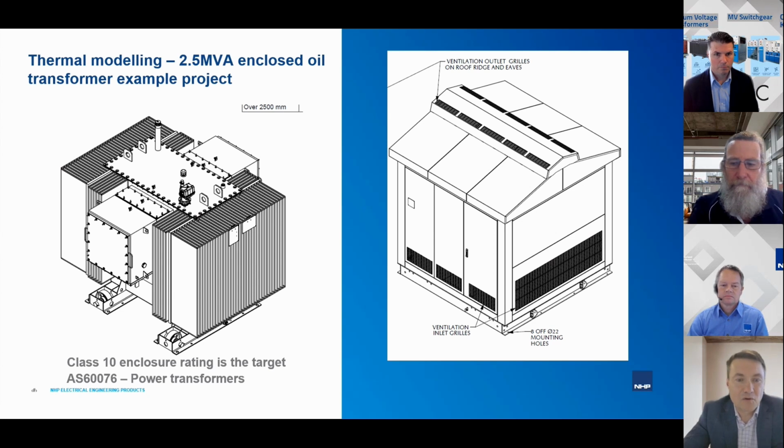So therefore, the transformer was not designed to accommodate additional temperature rise within the enclosure. If that was specified in the beginning, it would have been designed that way, and therefore the combination of transformer plus enclosure would still deliver 100%.